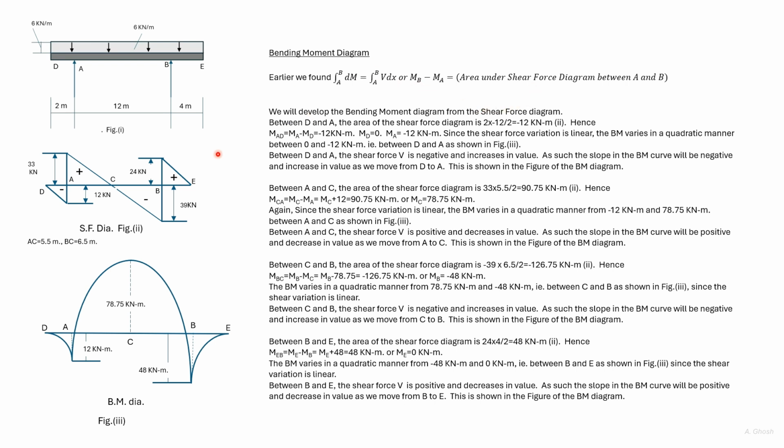The manner in which we develop the shear force diagram from the load diagram, in the same manner we'll develop the bending moment diagram from the shear force diagram. Bending moment diagram will be developed in tandem with the shear force diagram and will constantly use the shear force diagram and this equation.